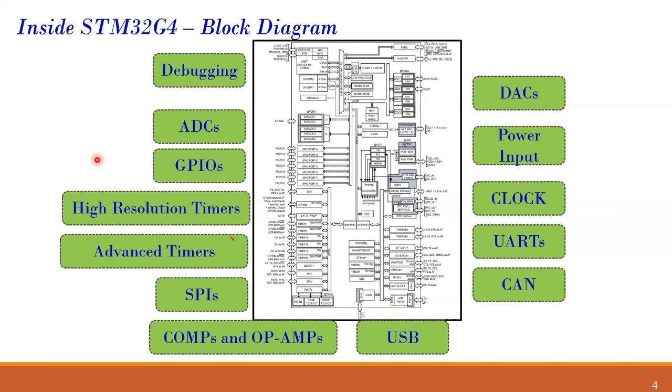These are all peripherals which we would otherwise require with an FPGA. The difference between the microcontroller and the FPGA is that in the microcontroller, all these peripherals are present inside. But if you are using an FPGA, like the one which sir has been using, as we discussed, you require an ADC driver, a DAC driver, an ADC and a DAC.